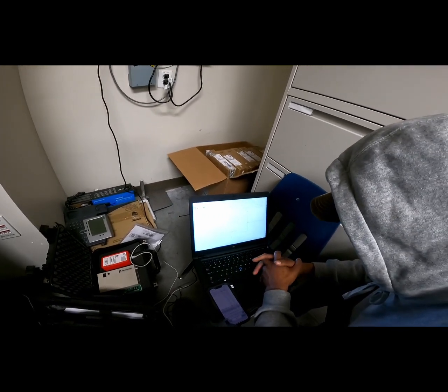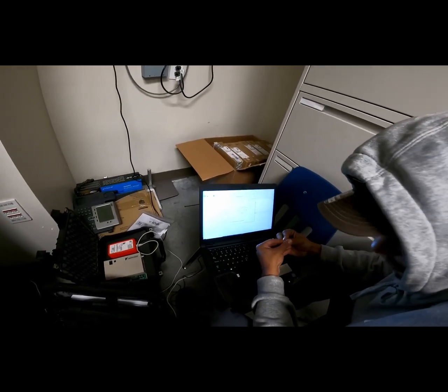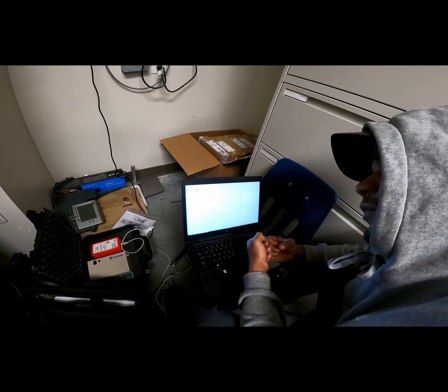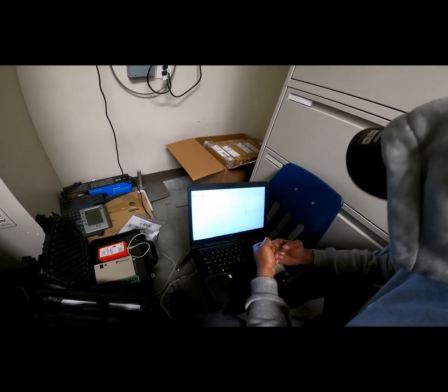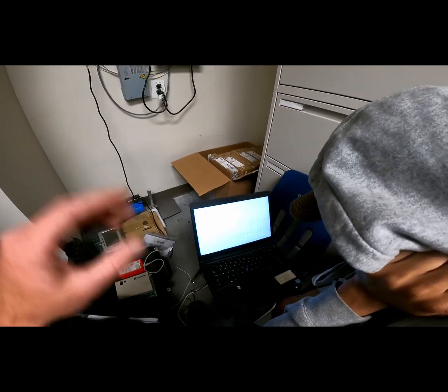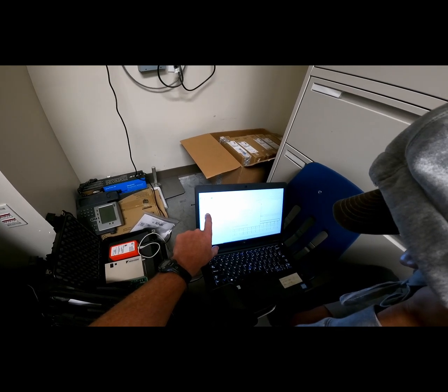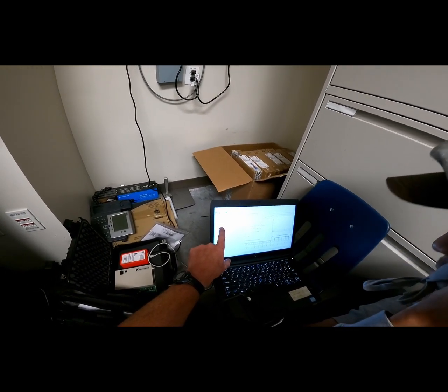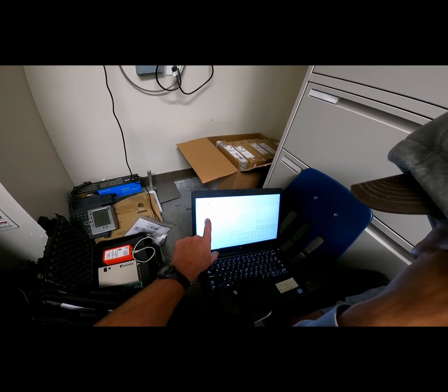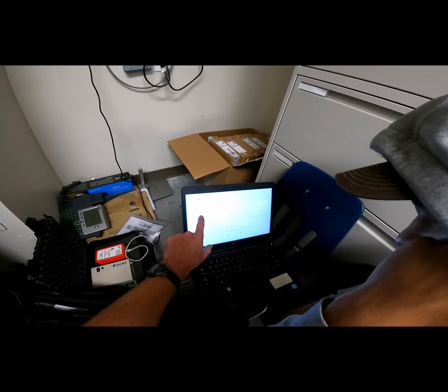Okay. In order to perform test mode on one of these units, essentially running it in full blast, so that you could extrapolate how well it's running from the data that you see, you have to monitor and then drive operation of an outdoor unit. When you see an outdoor unit, it'll be denoted as OC. If it has a follower, so this is the leader unit, this is a follower, and this is a branch controller. But now you see we got another outdoor unit popped up.